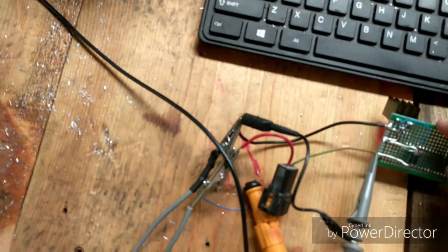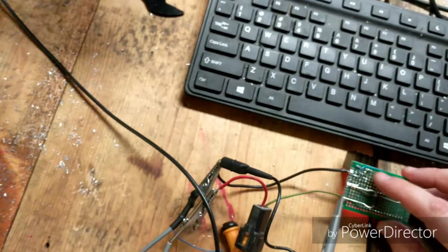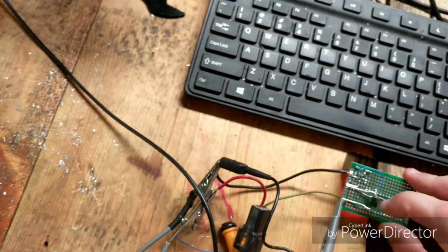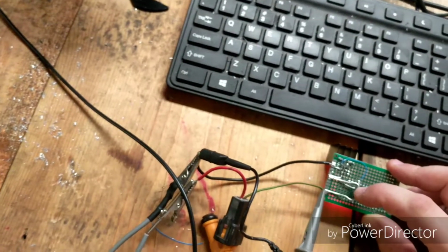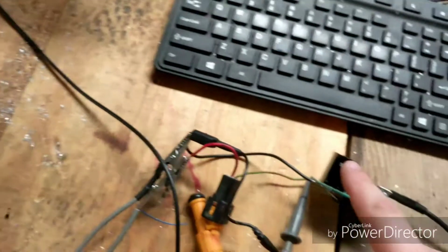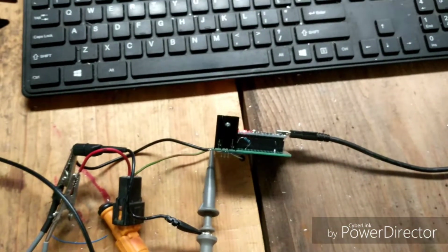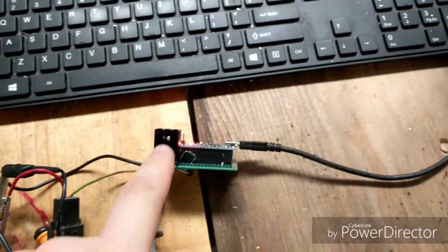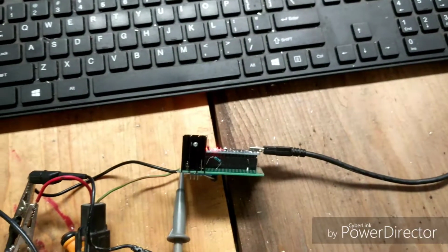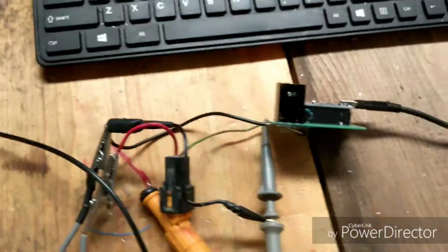I'm anticipating putting in an optocoupler to protect the microcontroller, as well as some protection diodes, dropper resistors for current limiting, things of that nature, and then scale it up. I'm still debating if I want to do one MOSFET per injector that I plan on incorporating, or if I want to be able to run multiple injectors off of only a couple of MOSFETs to try and keep costs down.